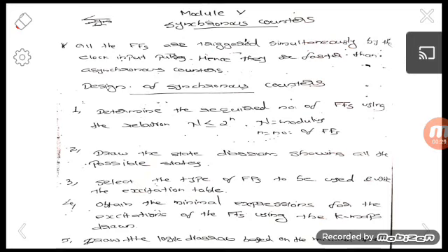In the case of synchronous counters, all the flip-flops are triggered simultaneously by the clock input pulses. But in an asynchronous counter, we have seen that the output of the first flip-flop is given as the clock input of the next flip-flop. Here, in a synchronous counter, we give a single clock pulse to all the flip-flops we are using. Hence, this counter is much faster than an asynchronous counter.